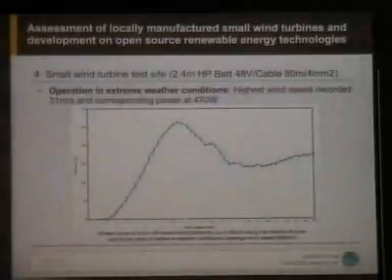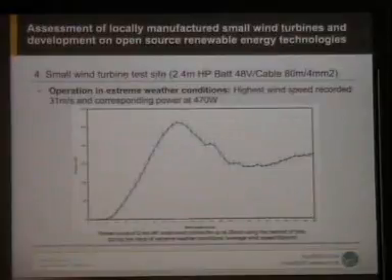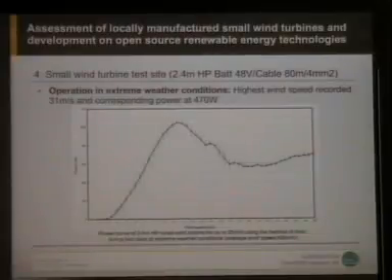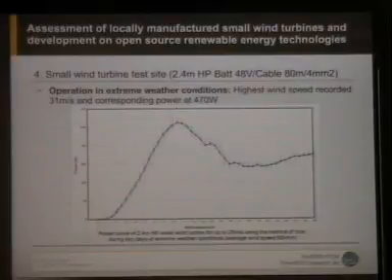Okay, one slide more. This is very interesting. At some point we had severe storms, and we thought, okay, let's not turn the turbine down. Let's not close it. Let's see what happens. And we left it at these kinds of values. We had a 31 meters per second wind gust, average wind speed 82 kilometers per hour for 2 days. So it was just furling constantly. We managed to get this power curve until 25 meters per second, and it's quite impressive that it's so robust, nothing happens.